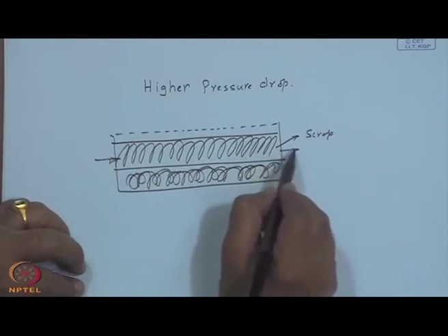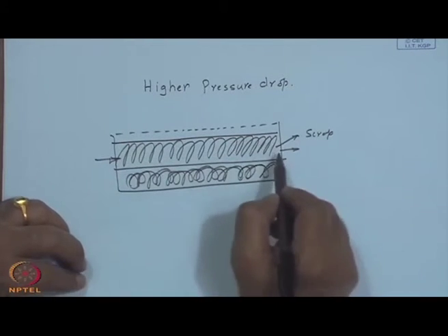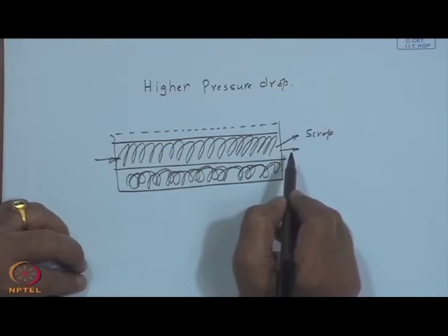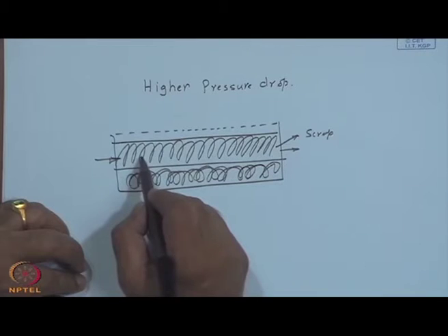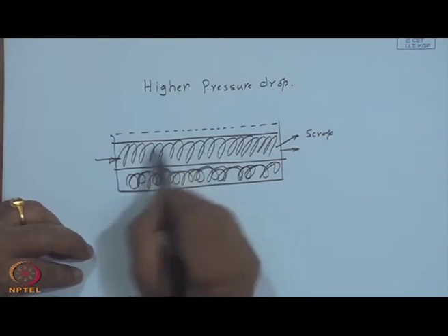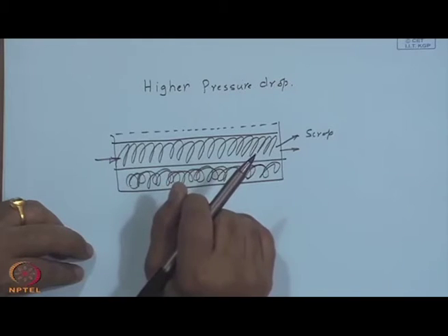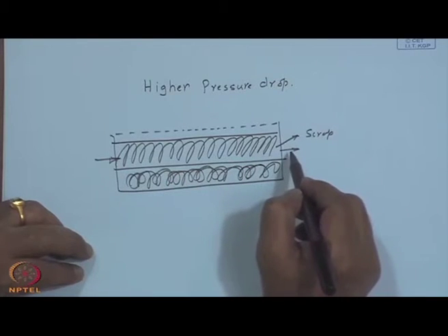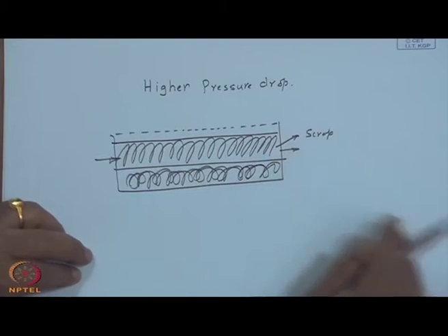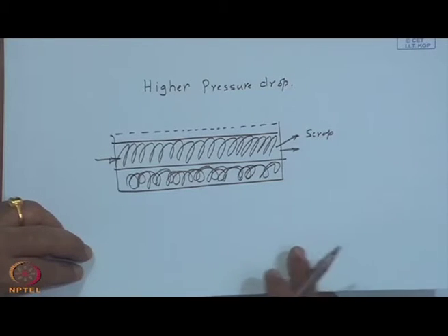Now, this has got the advantage that the fluid will be going up and down and there will be better heat exchange. At the same time, you have the disadvantage that the heat capacity will be very large. The collector to get heated to that warm-up temperature that we were talking about will take longer, and the pressure drop will be enormous. We have not talked, though I will not discuss very much about this particular arrangement, the evacuated tubular arrangement.